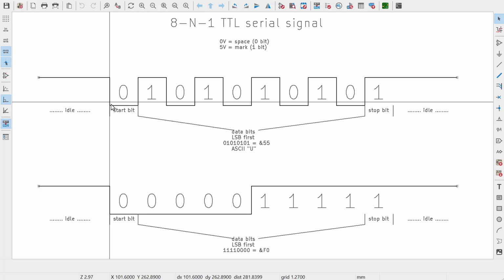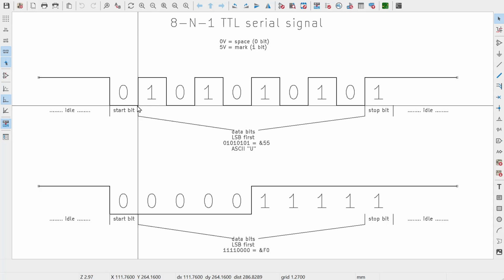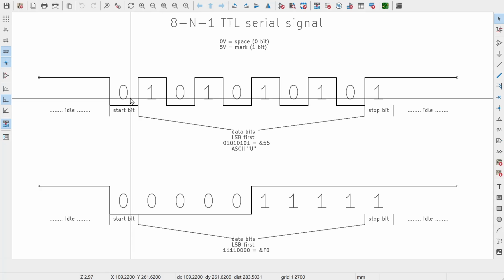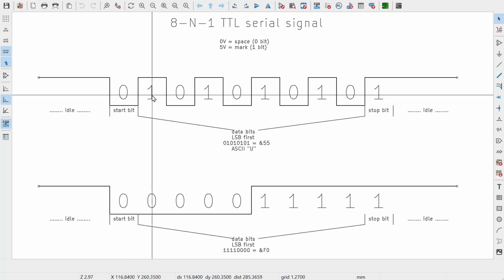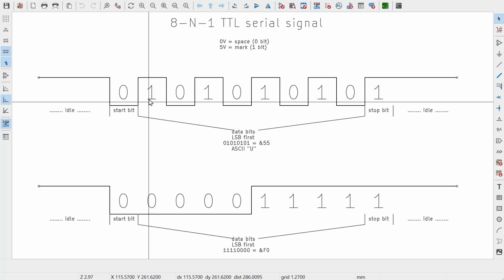We already calculated, I think, for the transmit circuit that 1 bit duration is 35 ticks of that counter, so we had a 40103 down counter that was counting down from 34 through to and including 0 to count 35 durations to get there. So based on that, I'm expecting to have to add another 17 or so onto that, so this will probably be 52, is that correct? 35 plus 17. So we might want to set 51 and then count down from there. I can't remember exactly what I did, but we can check in a minute.